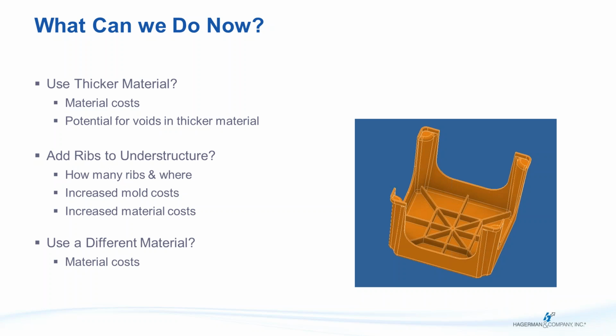You've got to change the molding situation. When you run with thicker material, you also have a risk of voids and pockets, gas voids, and seam lines in that material. All of that's going to come together to make it weaker. The ribs could actually reinforce it.